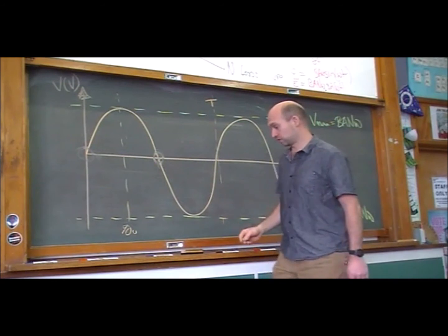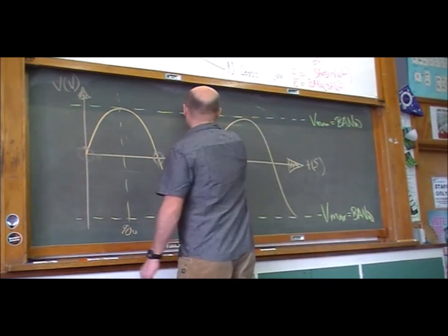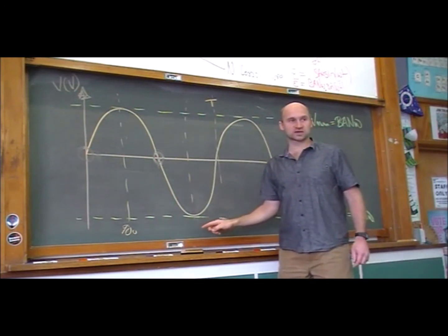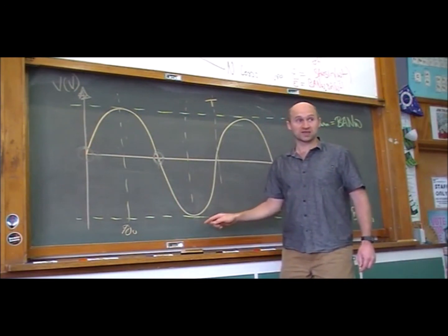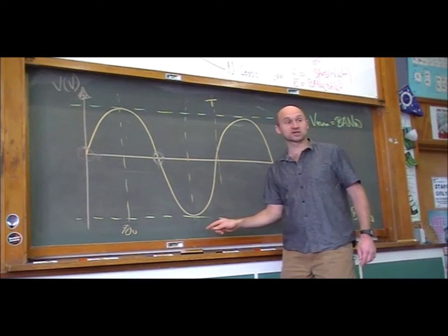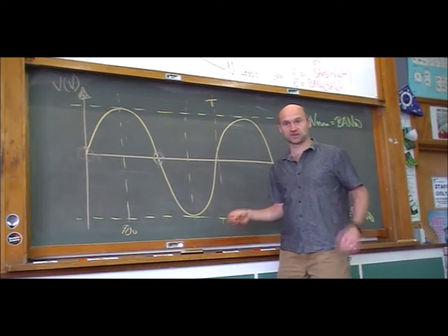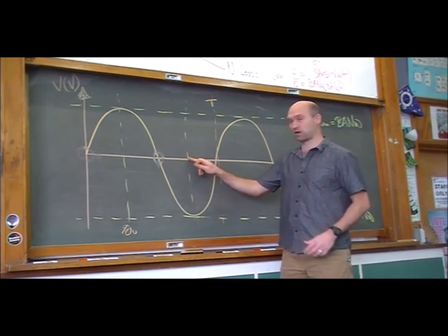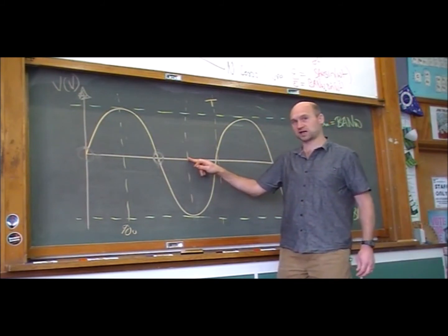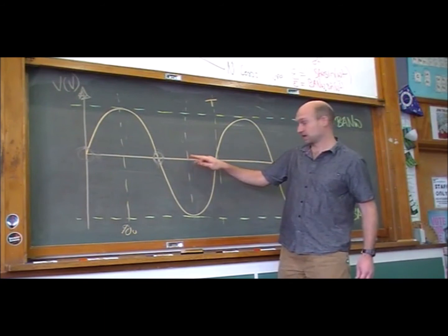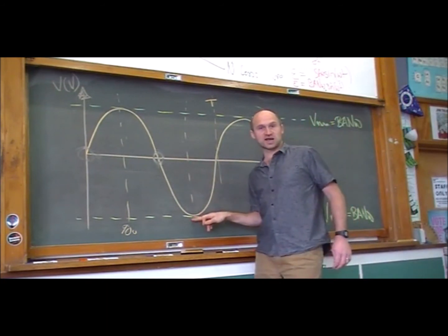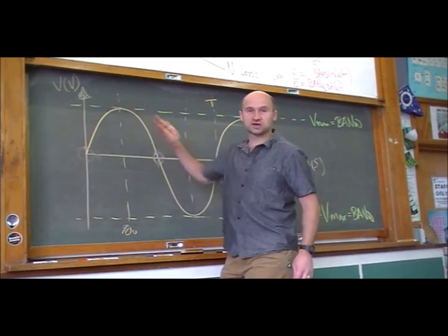Then another quarter of a turn on, we're over here, and once again, we're getting that maximum rate of change of flux at the same time as we've actually got zero flux through the coil. So if we think about how much magnetic flux through the coil, zero, rate of change of magnetic flux, maximum, so induced voltage, maximum.